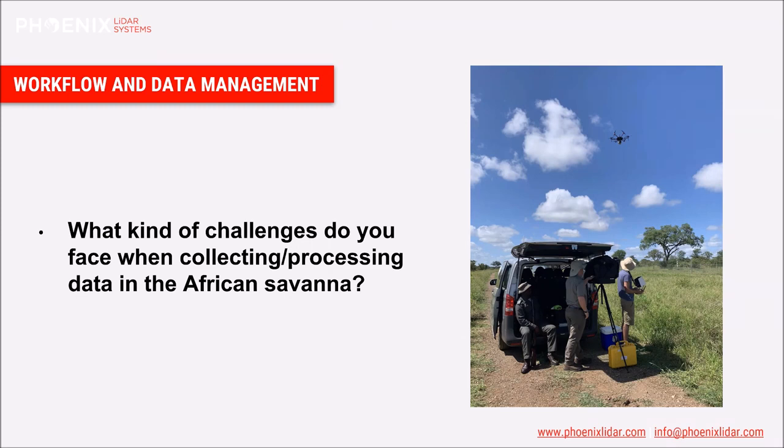You have to think, the drone's in the air and there's an elephant here. It's a potentially dangerous situation. The other thing you have to take into consideration is if you have pieces of equipment you have to leave throughout the landscape, like our GPS puck we use for post-processing kinematics, the base reference station. We would sometimes be able to leave it in gated camps if we were close enough to the camp where we were operating that day, and obviously that helps remove the threat of animals. But sometimes we couldn't do that.